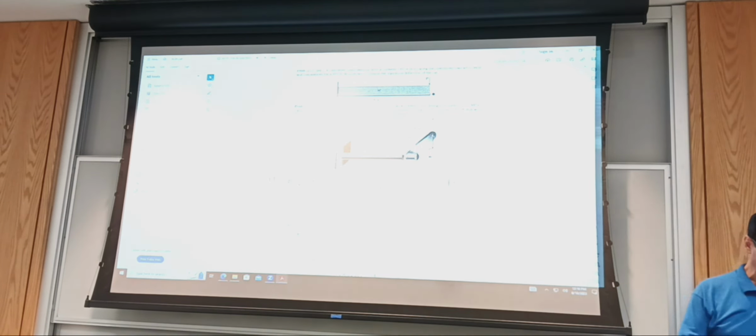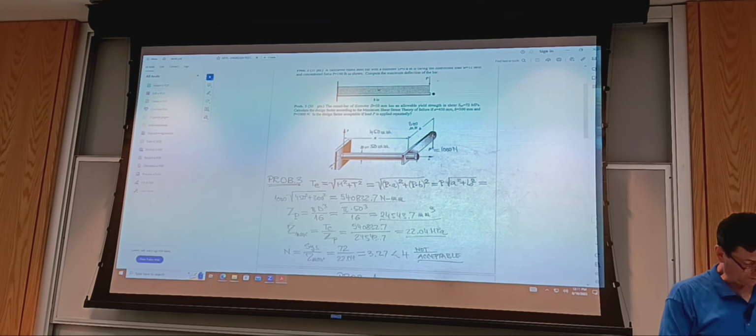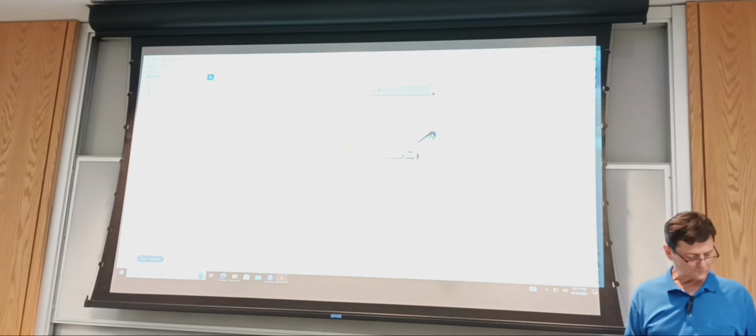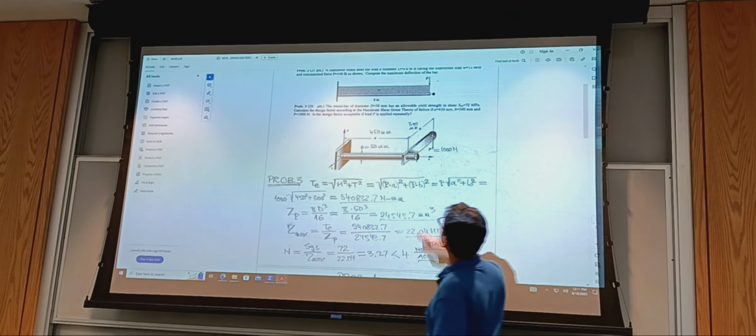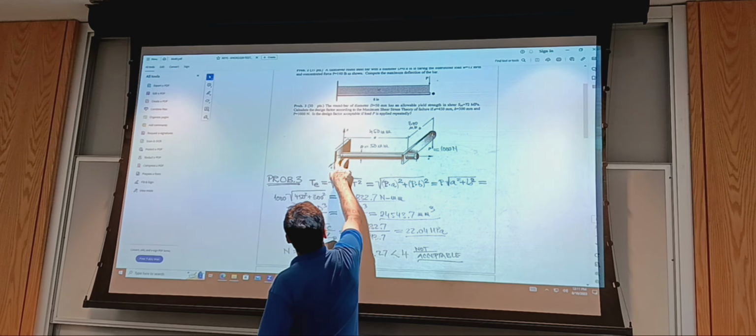Where is it in the book? The one with 4 forces. Let's see. I can project it. So we did a problem very similar to this one. It's the next problem, 1028, and so loads are down and offset. Here we have just one concentrated load, and being offset, what it does is twist the solid bar, 50 millimeter diameter. I changed this value in this one. So that's inducing the shear stress, and you have tensile bending on top. There's compressive below.